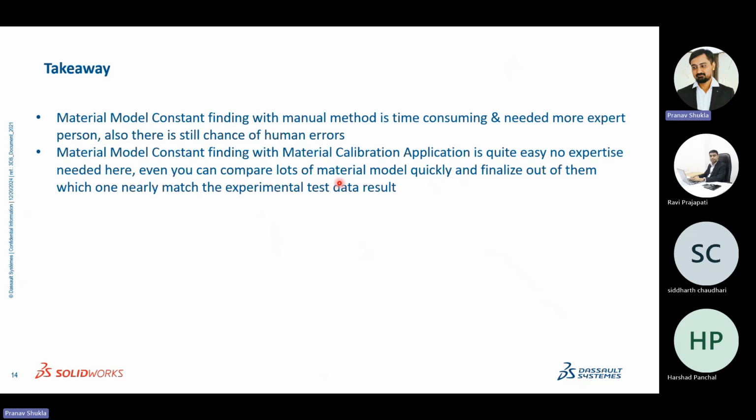You can even compare lots of material models, as I showcased previously. There are a number of material models available, so you can quickly check which material model gives you a result nearer to this data, and you can finalize that particular material model for your analysis out of them.